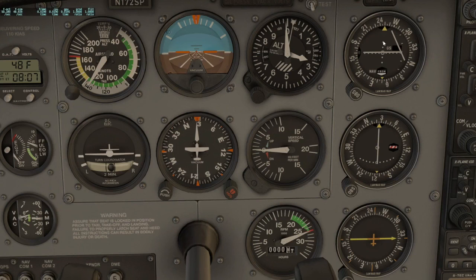You can actually keep the radial here and turn to 070, or you can actually pick that as a TO. So instead of a from radial, it's a TO, and we can select here 070 TO that we need to intercept, and that would be the 250 inbound.